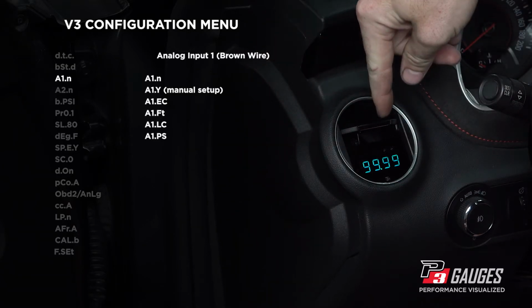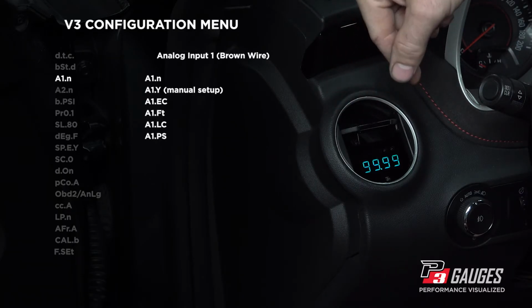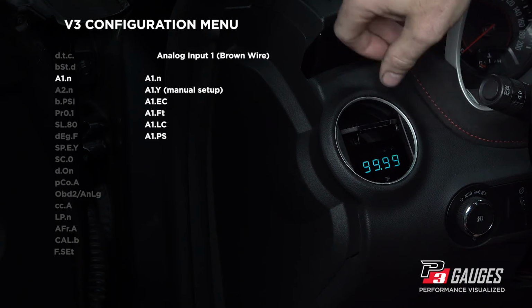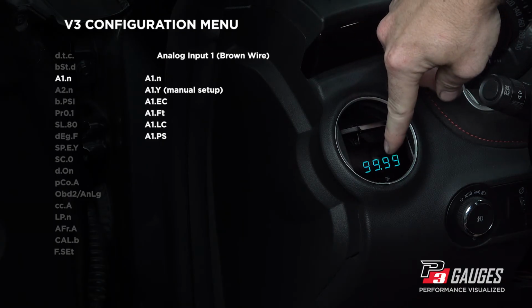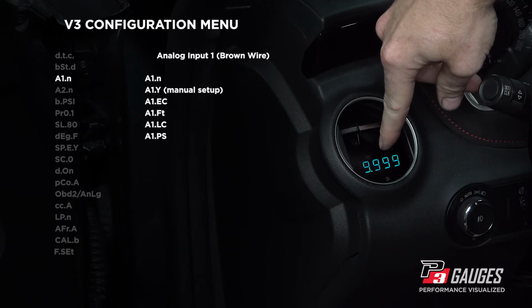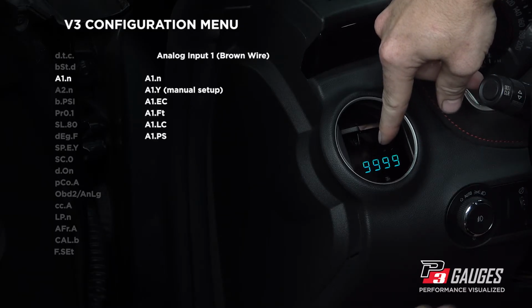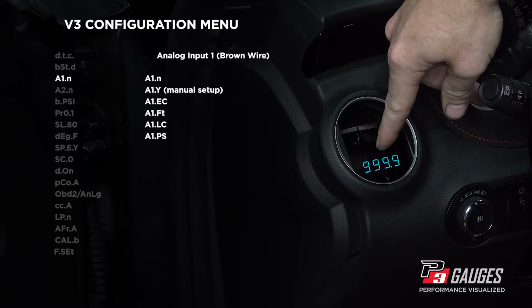And it's going to say A1.DP, which means decimal point, so analog 1, decimal point, and then it's going to jump to 4 nines. And you can see as we push the left button here, the decimal point is just going to move. So we've got 999.9, 99.99, 9.999, depending on what value you're reading, or no decimal point at all. So you have some options there.